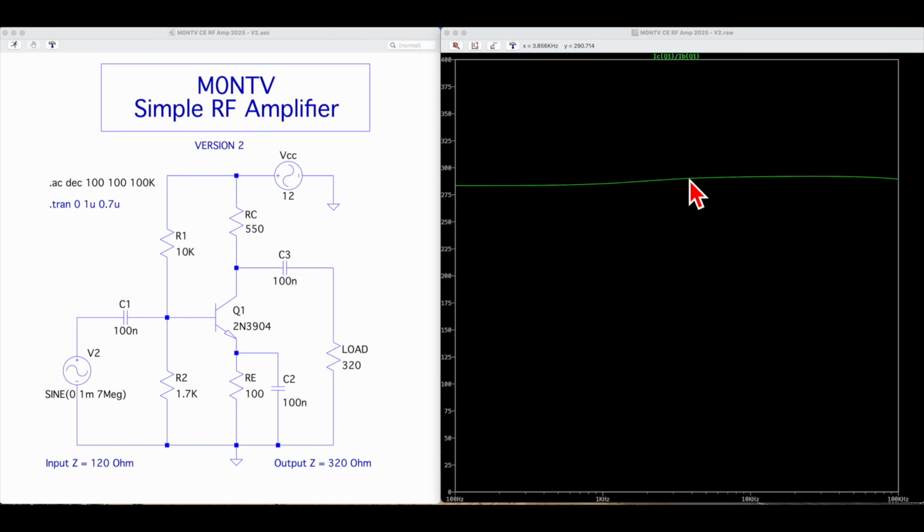So you can see why, if you're going to use this 2N3904 in an audio amplifier, it's absolutely fine to assume that the current gain that your audio signal is seeing as it works its way through the transistor is pretty much the same as the DC bias is seeing. So we can use this same value of beta.